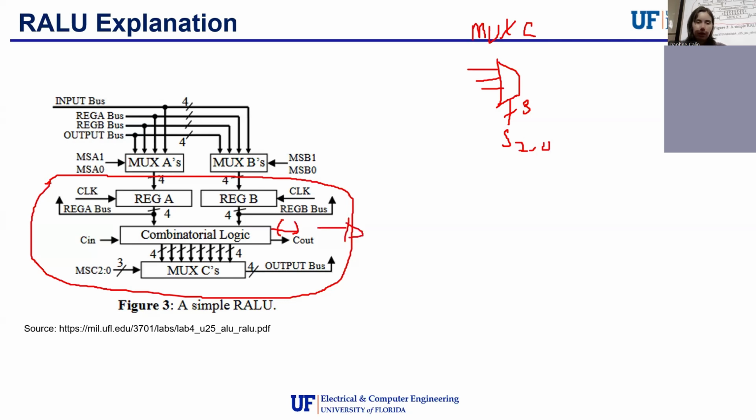So you might have something from register A being NOTed, and that output goes into one of these lines for the mux. So I have NOT and OR and whatever. And it just so happens that the thing you are putting into this multiplexer, like this ALU, is from a register.